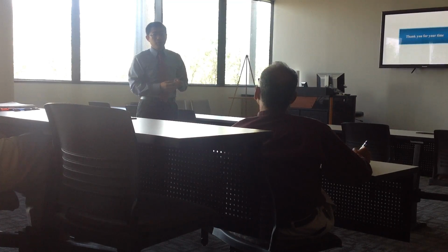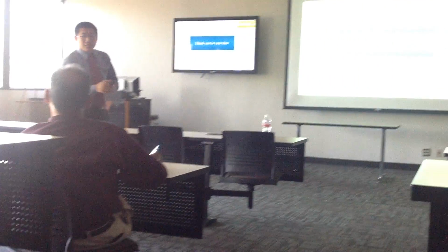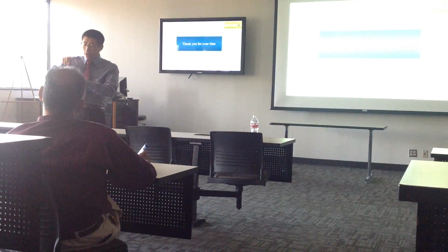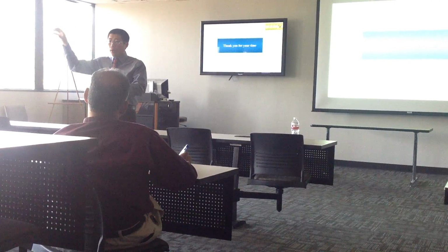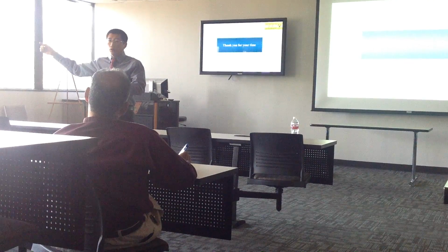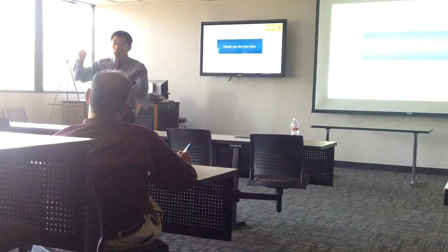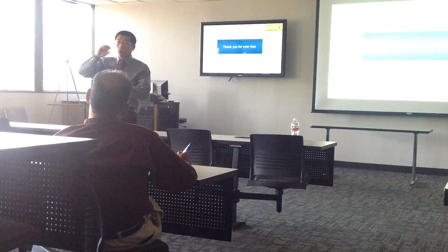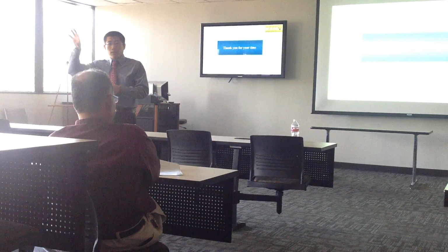So why did you choose SST gamma theta instead of the other models? Okay, good question. First, it combines two different models, the SST model and the gamma theta model. The SST model also combines two models, the K omega model and the K epsilon model. About 20 years ago they only had the K omega model, then 10 years later they had the other model, and now they have the SST model. It combines the advantages of these two models, so the SST model shows better behavior than the other models.